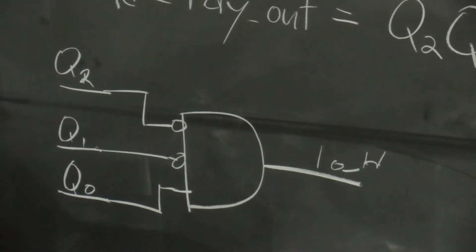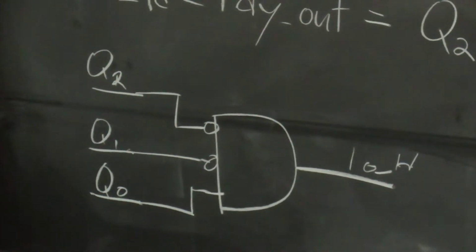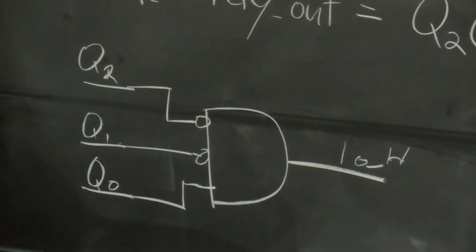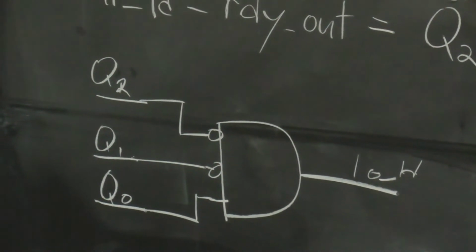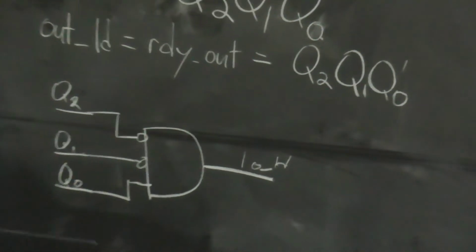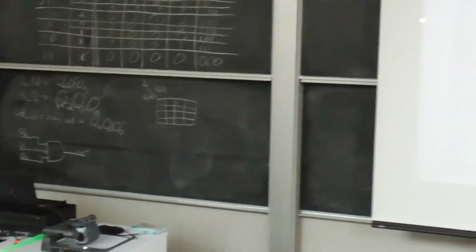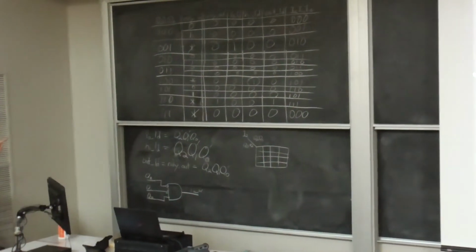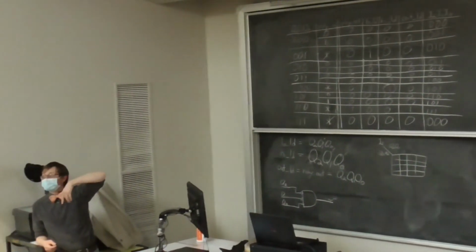Make sense? Yeah, well, mainly what I was wondering is because in the finite state machine, we set them to 1, but it never gets set back to 0. So I'm wondering why in our chart we don't have it 1, and then for the rest of the states it's also at 1. It's kind of just assumed knowledge about registers. With registers, you only load them, like that one, if that one was 1 for longer, like if we had don't care values instead, it would constantly be loading from data in.